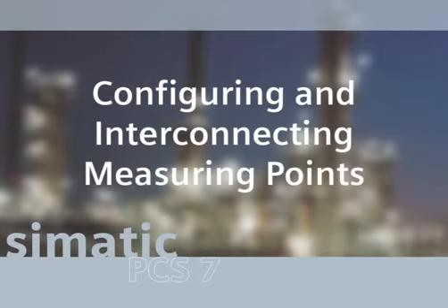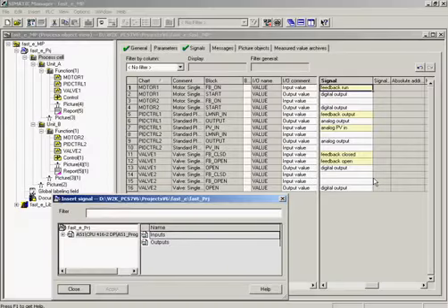In this sequence, we are going to show you how you can easily assign I/O signals to the individual charts and function blocks that are used in the application. We will use the symbolical names which have been defined previously and assign them to the corresponding measuring points. The signals are interfaced easily and conveniently in the process object view.